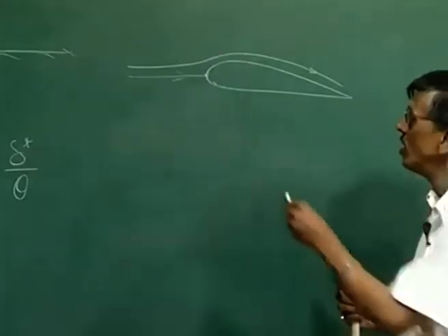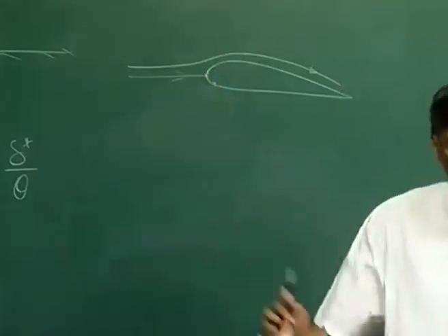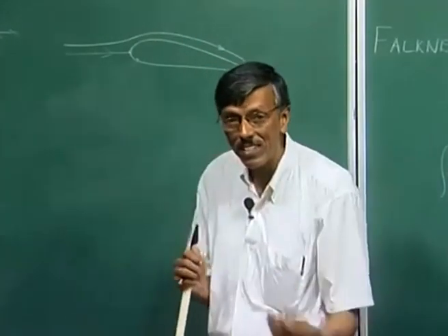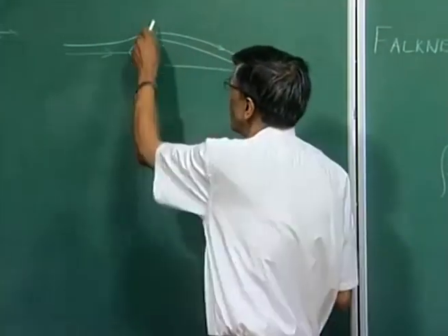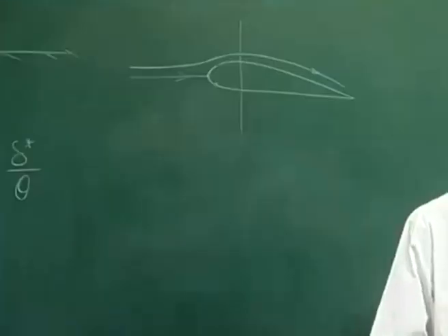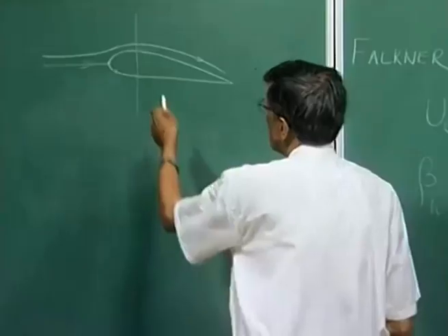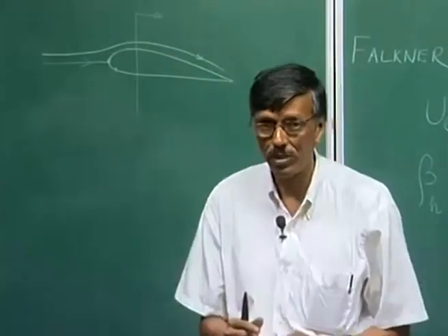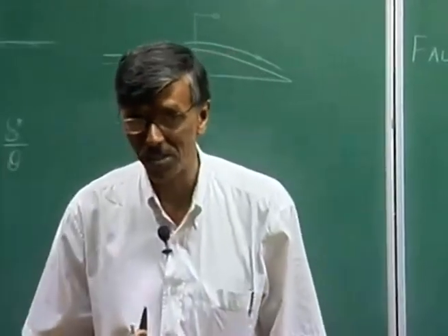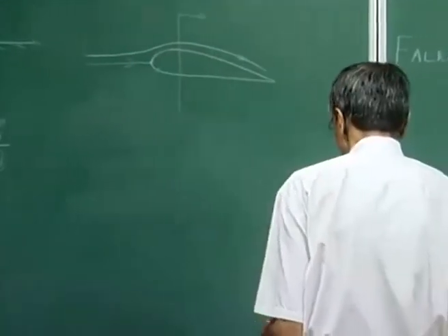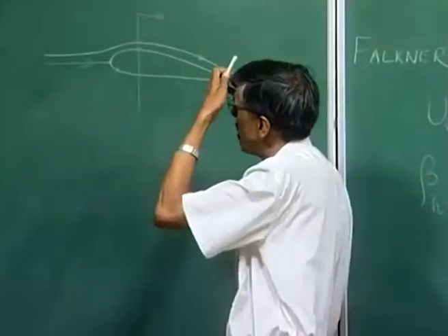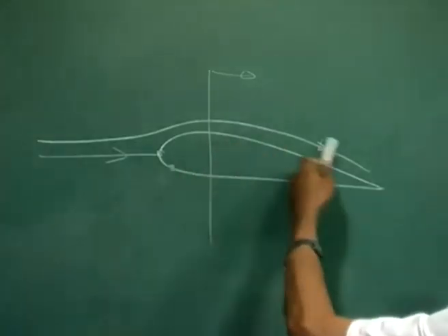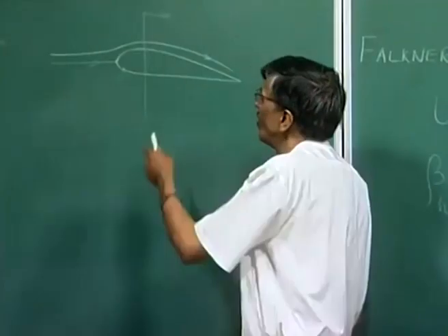In the early part of the flow, this is where of course stagnation point means flow has stagnated there, and then the flow actually starts accelerating from there, and the acceleration will go on till the position of the maximum thickness. Beyond the position of the maximum thickness, what happens? The streamlines diverge. So, that means the flow experiences adverse pressure gradient, right. So, you would see that in real flows, you would get an admixture of all. Okay. And this is what you are going to expect.